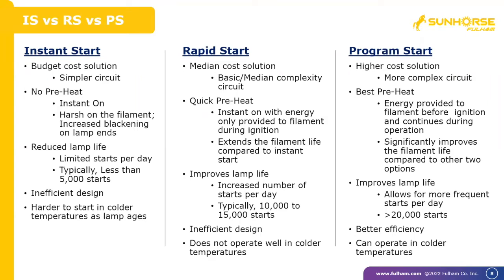So in terms of cost, the most effective one will be instant start. The downsides that come with that will be a reduction in lamp life with more and more cycles that happen with the lamp. Overall, with instant start, you will achieve fewer starts compared to a preheat design. As I mentioned, there is no preheat, so you'll tend to see more and more blackening of your filaments over time as you use the lamp. With instant start, it is not recommended for cold applications.